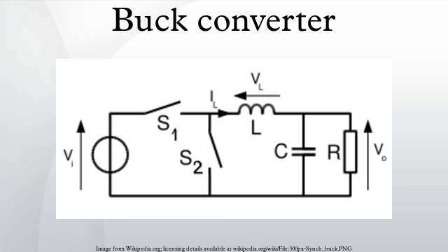But this doesn't take into account the parasitic capacitance of the MOSFET, which makes the Miller plateau. Then, the switch losses will be more like this when a MOSFET is used for the lower switch. Additional losses may occur during the time between the turn-off of the high-side switch and the turn-on of the low-side switch, when the body diode of the low-side MOSFET conducts the output current. This time, known as the non-overlap time, prevents shoot-through, a condition in which both switches are simultaneously turned on. The onset of shoot-through generates severe power loss and heat.